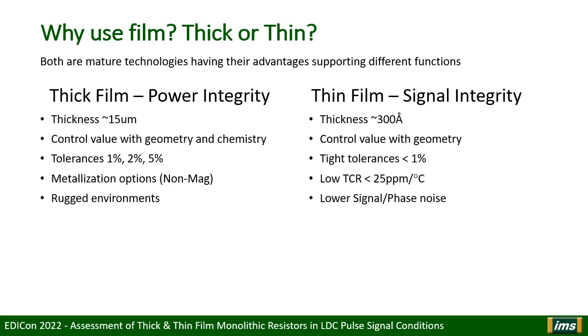Thick film processes control resistor value with the deposition of a designed geometry containing different proportions of a conductor and non-conductor that in most cases are trimmed up to a desired value by laser ablation. They're hermetically sealed with a passivation glass for protection from moisture and other damaging elements that can be present in the air.